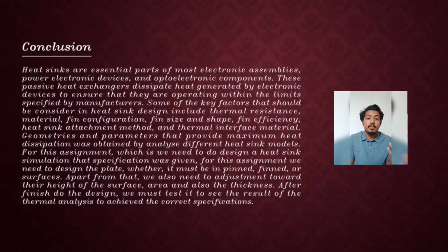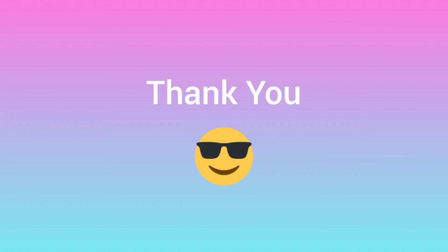For the assignment, we need to design a heatsink simulation to the specification given for the assignment. We need to design the plate, whether it must be pin, fin or surface. Apart from that, we also need to adjust the height, the surface area and also the thickness. After finishing the design, we must test it to see the result of the thermal analysis to achieve the correct specification. That's all from us.